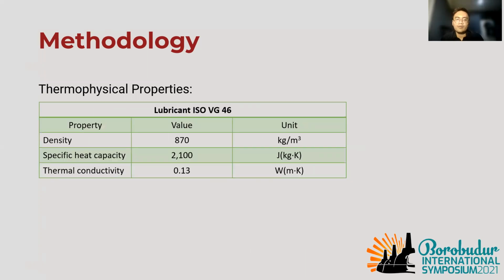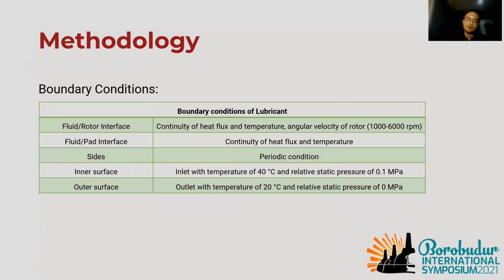These are the thermophysical properties of the lubricant ISO VG 46. We define the density, specific heat capacity, and thermal conductivity as an input on ANSYS Fluent.